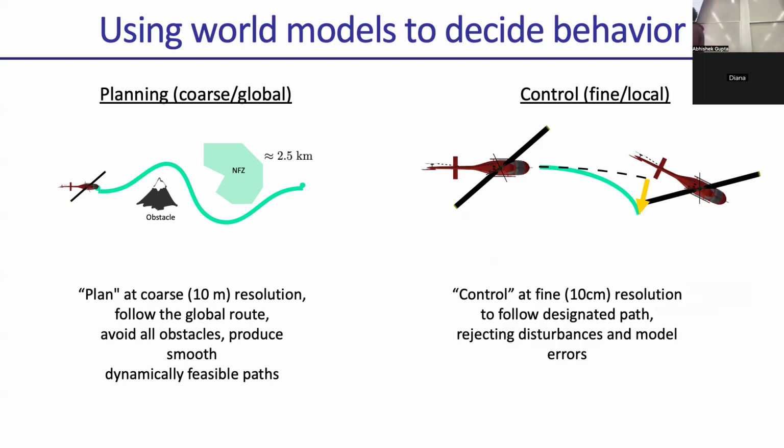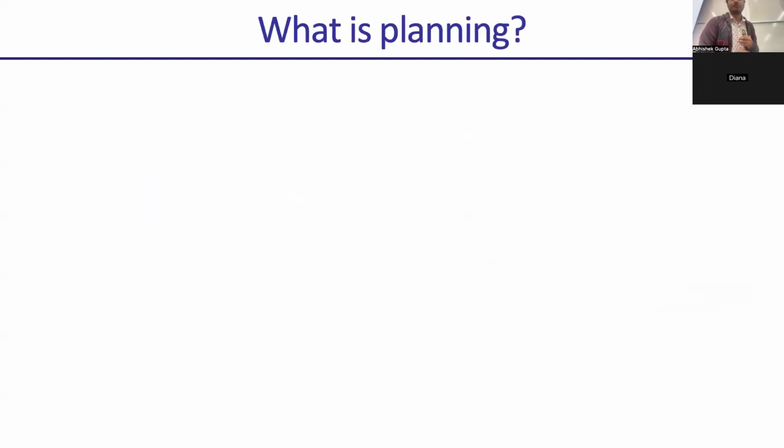That's right. Yeah. So you've introduced this hierarchy, and so you assume that you will plan with waypoints that you can get to. And so you need to make sure. Often there's this thing Sid is going to cover called dynamic planning, which is saying, how do you make sure that the waypoints that you choose are dynamically achievable, right? You might have things that are not achievable, and then your whole hierarchy breaks. And so you need to be careful when separating things hierarchically, but you never want to plan at just one level of resolution. It's pretty inefficient.